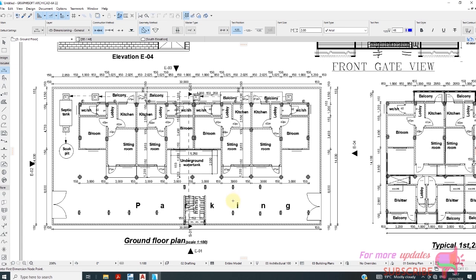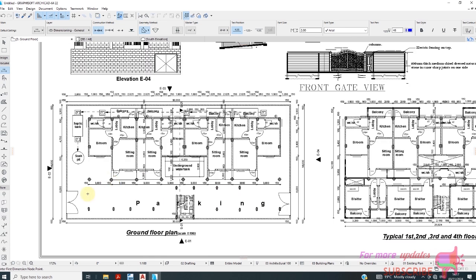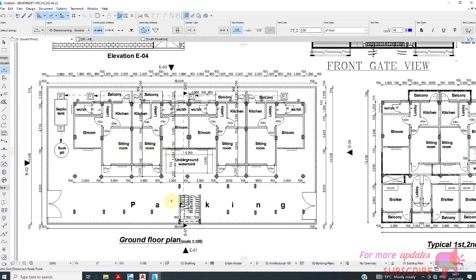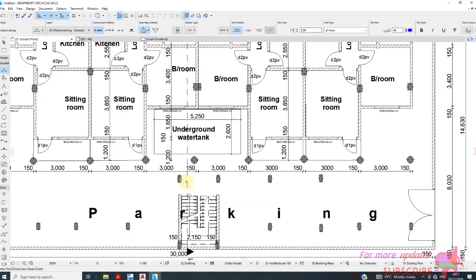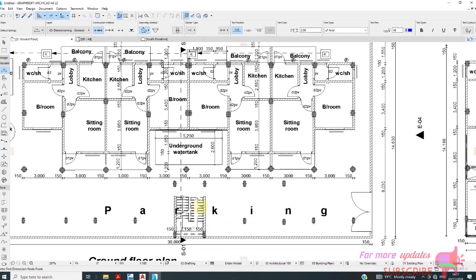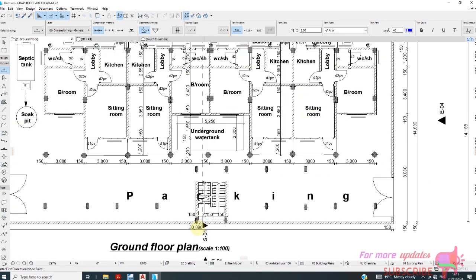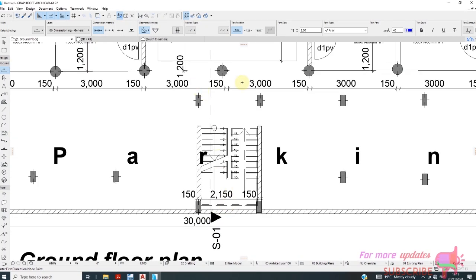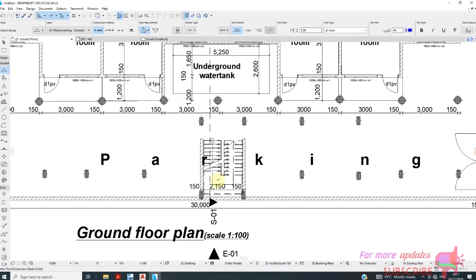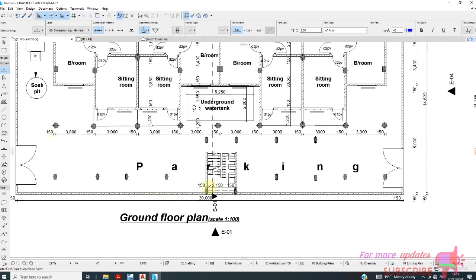So we need to load these front side of our column apart from this staircase region, because you can see this wall again is going down to here. Apart from only this staircase region, we have to load the wall load in these beams, and I'm talking about these beams here.